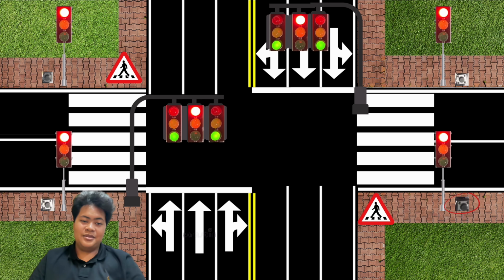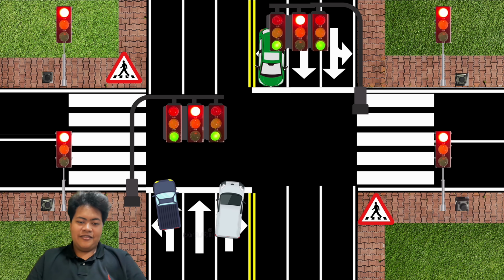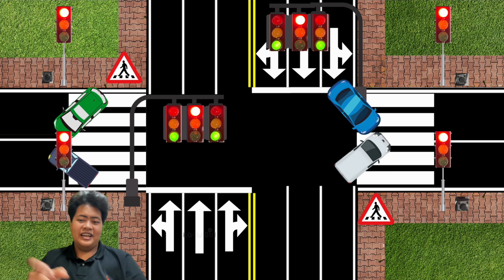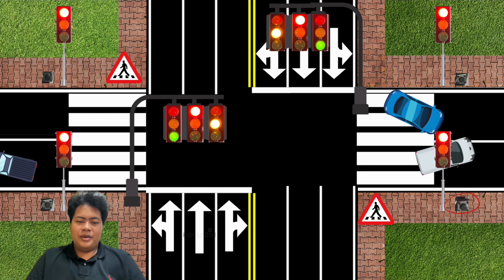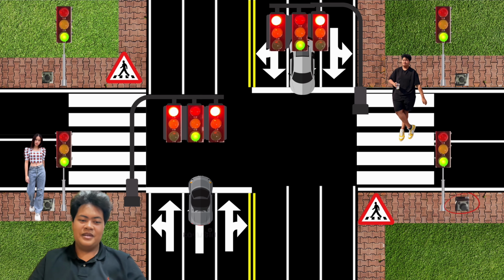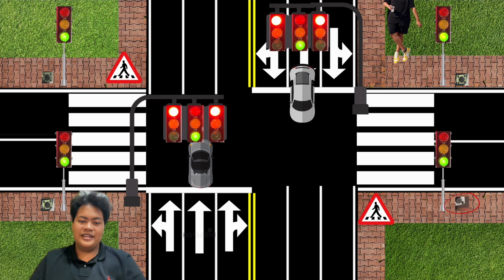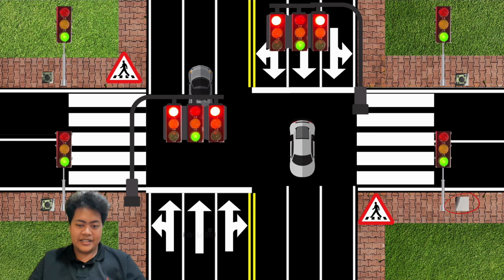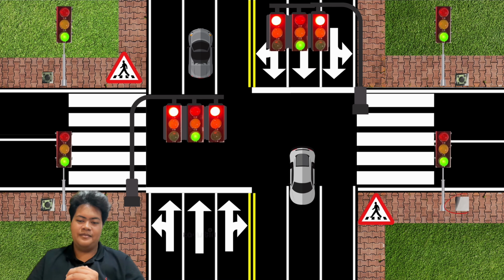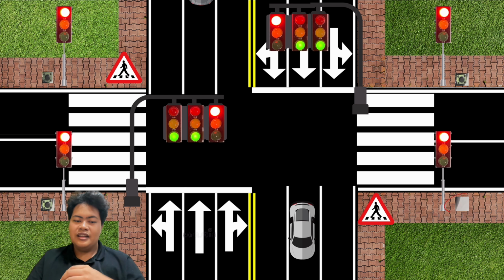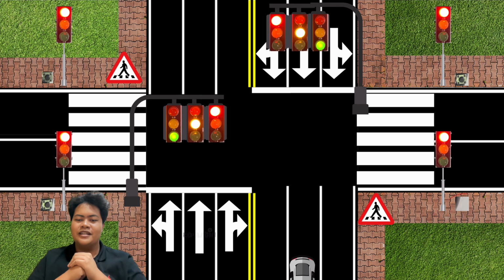Let's move on to the last one. During an active pedestrian crossing phase, the pedestrian light is already green, right? But if someone presses the button again while the light is still green, nothing happens. The system ignores the input since the crossing signal is already active. The system continues running the current pedestrian phase as usual, and when it ends, it moves on to the next traffic cycle without being interrupted. This prevents unnecessary delays or repeated crossing triggers while pedestrians are already walking.